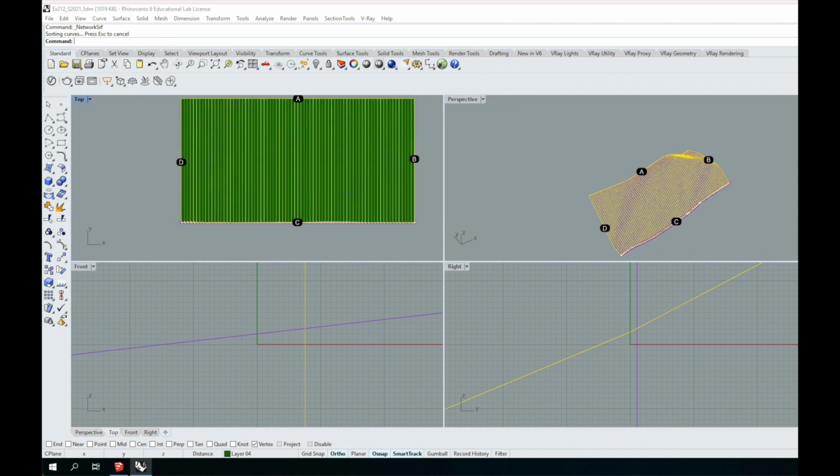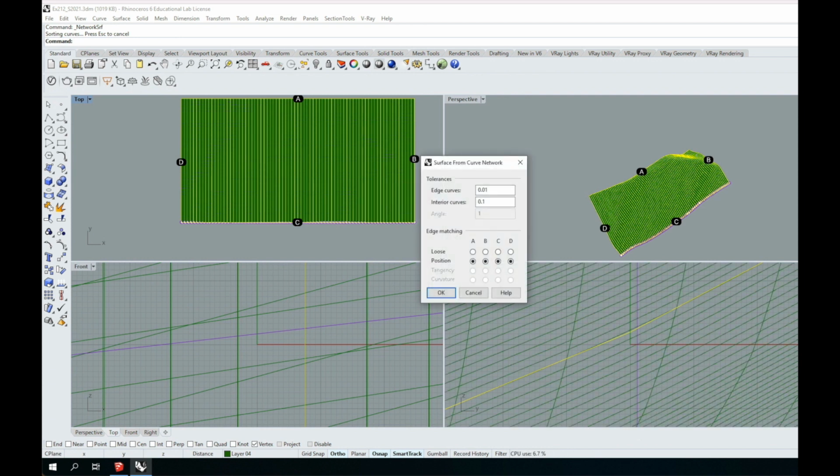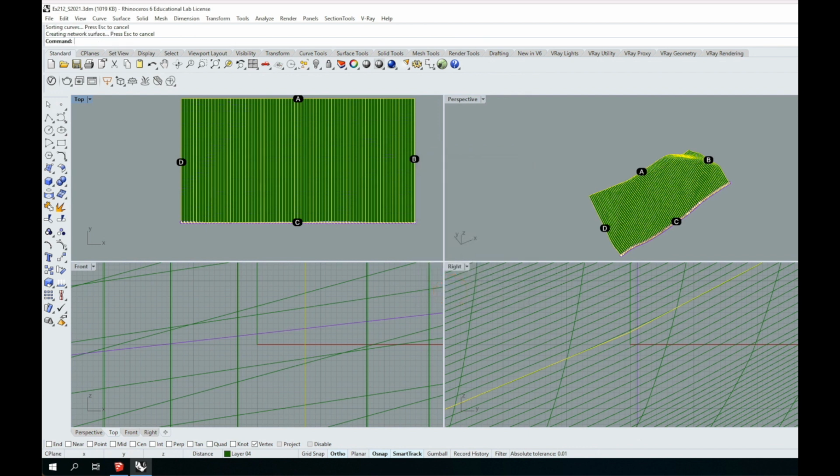And you can tell that this builds the preview a lot faster. So it's fewer curves, it's a little bit less accurate, but it's going to work a little bit faster on the computer. So there we are. We'll leave my default values there. We'll go ahead and say OK. And it will go ahead and process and build out that next piece of the surface. So we'll give it a little bit of time to chug through its calculations here.